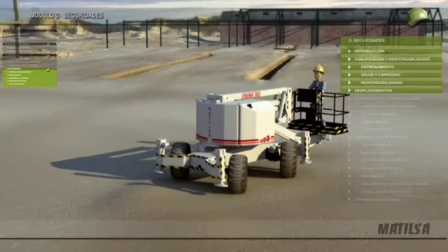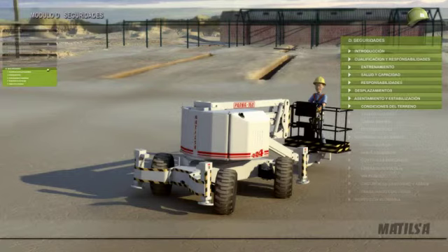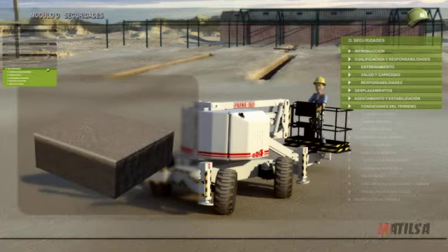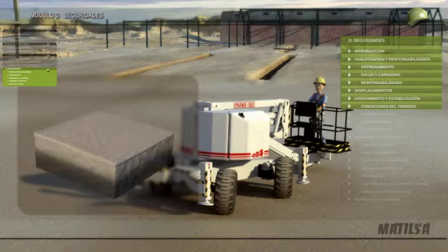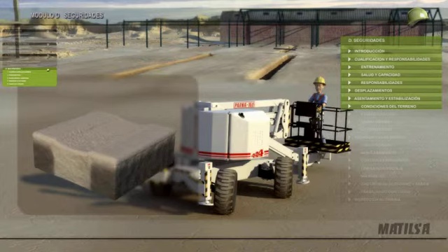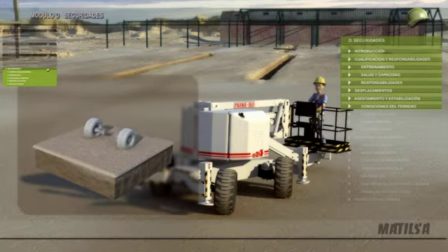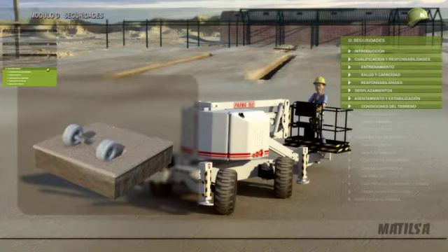Settling and stabilization of the workplace. The land where the platforms work has to be stable. A non-stable ground may cause an overturning accident. Here are some typical conditions of land that should be avoided at all times. Non-compacted ground. Earth or other types of material that have been placed without being compacted. Ditches are usually in areas of work that could not be compacted and may bring about the lack of stability of the platform. Bear in mind the weight of the machine itself, since this may bring about the sinking of the ground and, as a result of that, the falling of the platform.